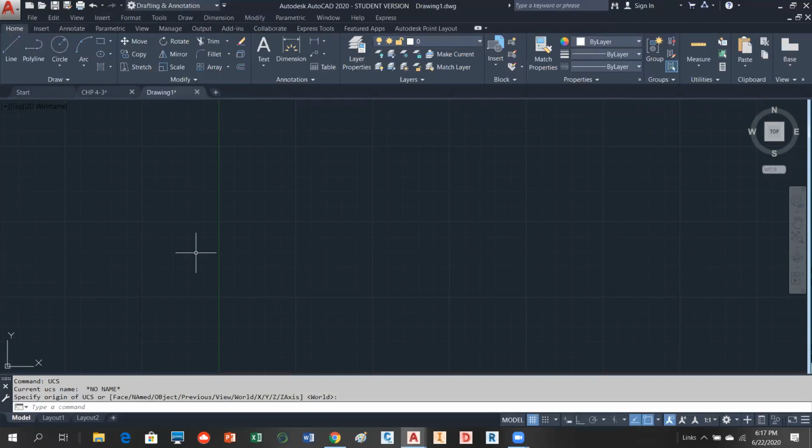So here's where it's going to get interesting for us. So why do we have the ability to manipulate that UCS? Well, the answer is so that you can work off of objects that aren't necessarily parallel with either this line or this line. So for instance, let's just take and draw a line anywhere on the screen. Okay, so I just want to draw a line anywhere like that. Okay, so I have no idea what angle that line is with respect to the UCS. So if I'm trying to define things off of this line, I really can't do that very easily, okay?